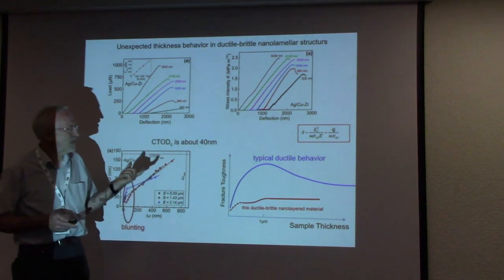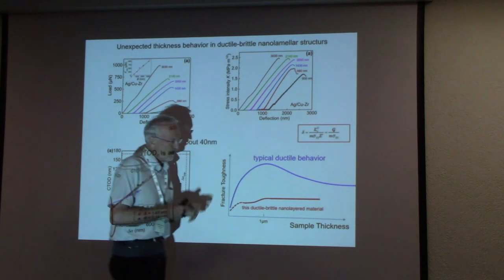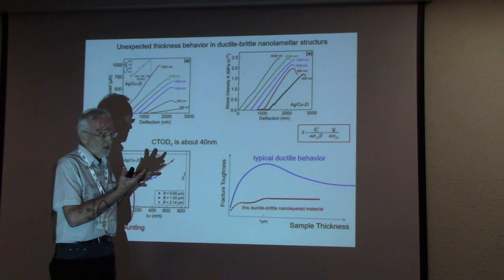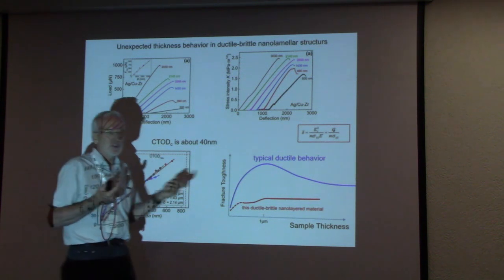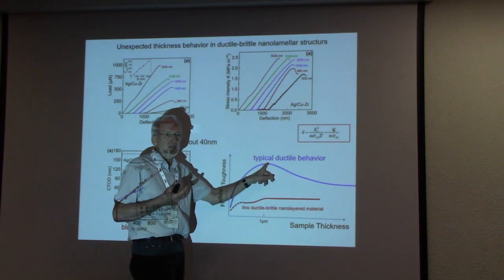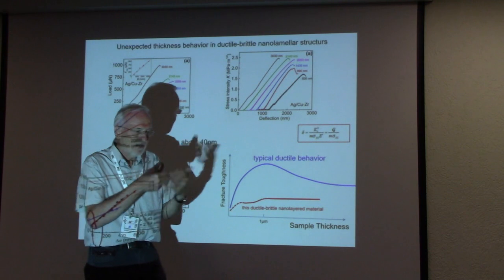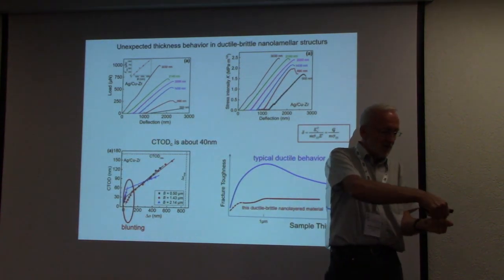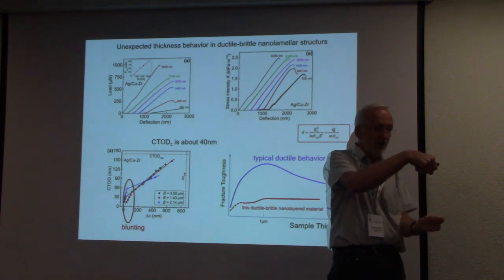Yes? What is the reason for this increase in ductility? The reason for this increase in ductility is that in the plastic zone, in front of the crack, most of the volume elements are under plane stress condition when we come in this region. The generation of pores is strongly affected by the tension, the stress in the loading direction.